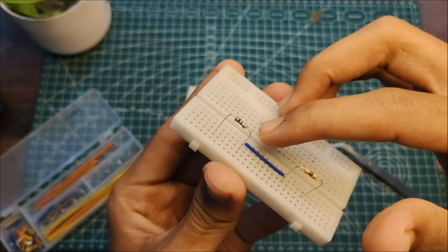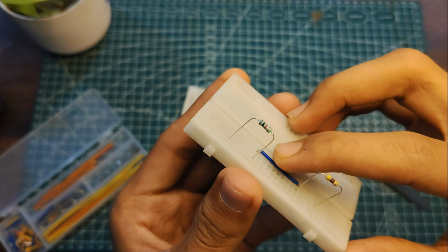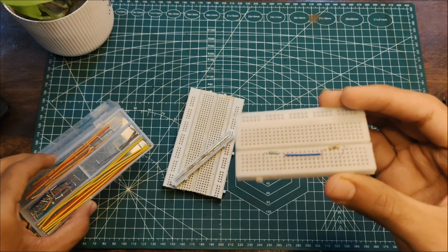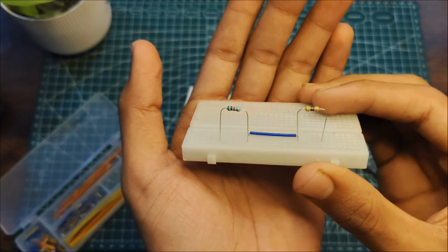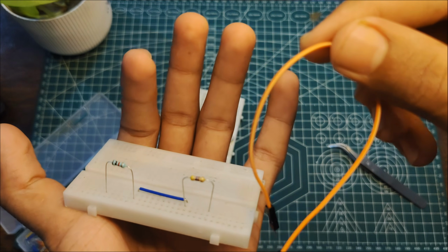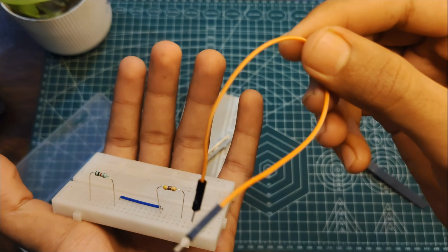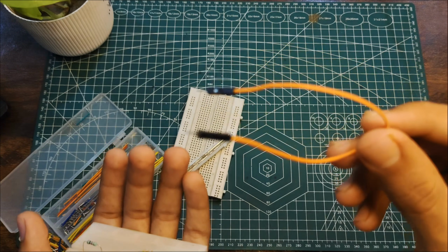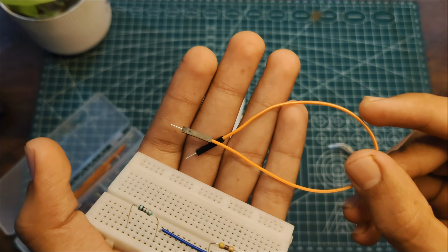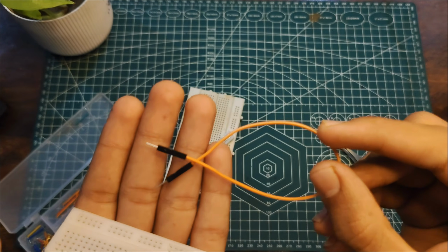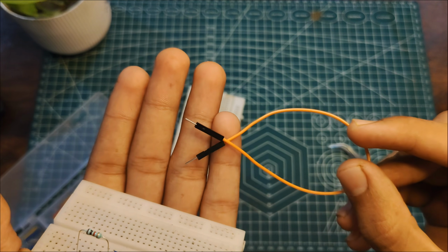So these are much preferred when you are working with a larger circuit, and very important if you are working on a better prototype, because when we go with extra length of wire, we are also introducing extra resistance, or it could have more noise. Most of the time the quality of this kind of jumper wire is not that good, and it could give us a hard time building some circuits.